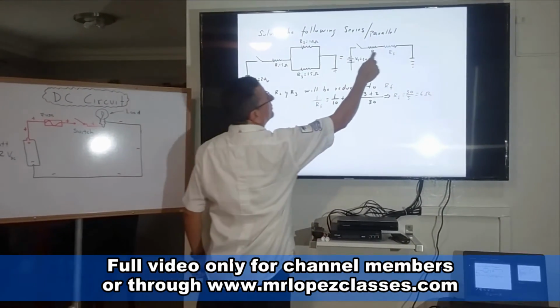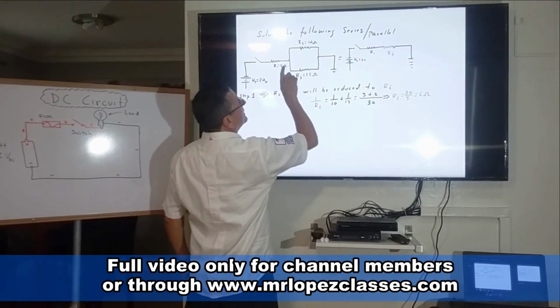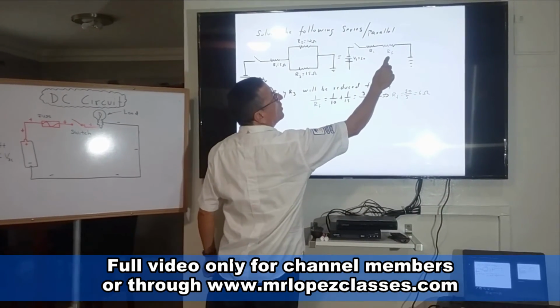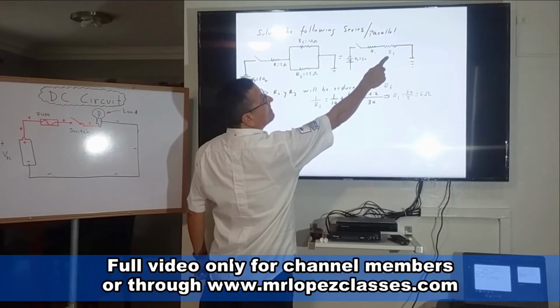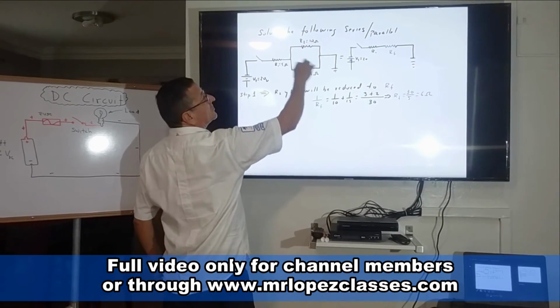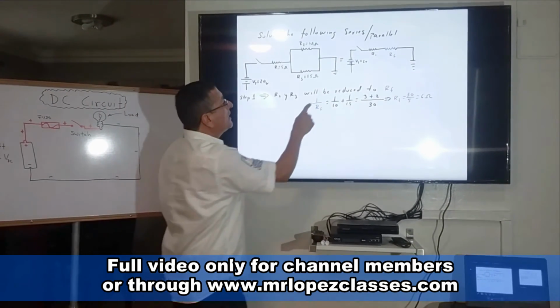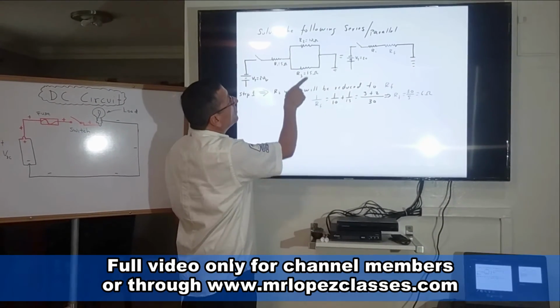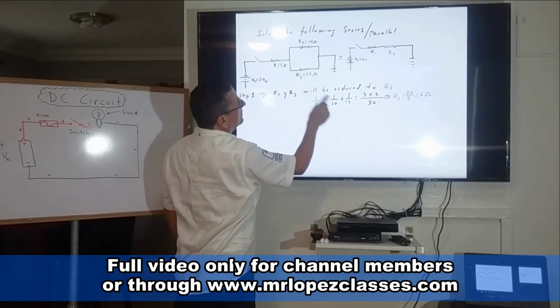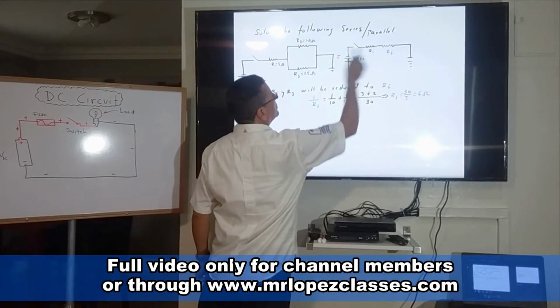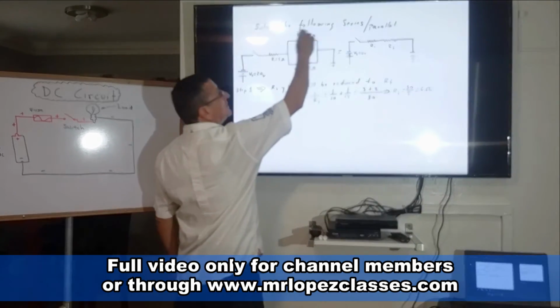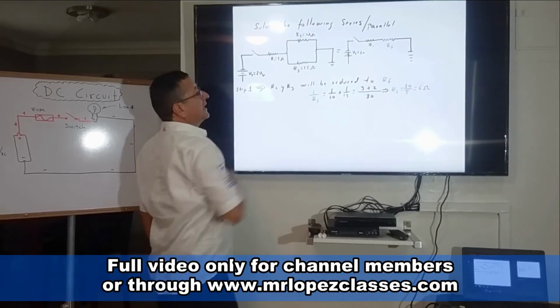The first one, resistor number 1, is right now in series with this one, the blue one, RF. But RF is the solution of this small parallel. What is the meaning of that? 1 divided by RF will be equal to 1 divided by 10 plus 1 divided by 15, because this resistor RF is the solution of this small parallel.